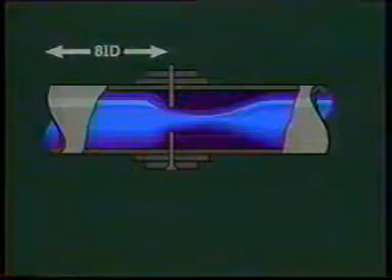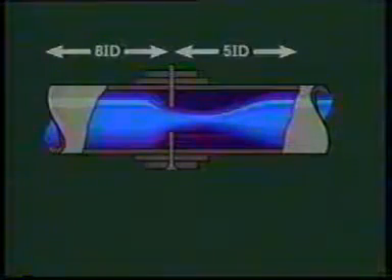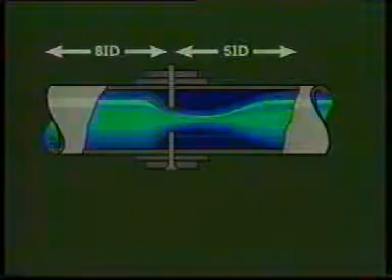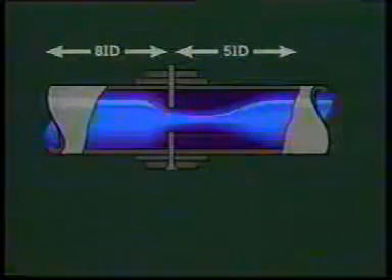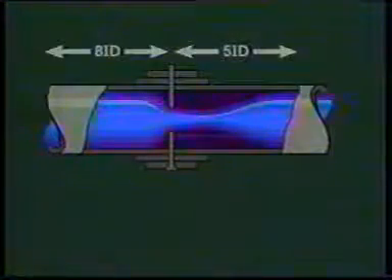The orifice flange should be installed in the line so that there is at least 8 pipe diameters of straight run on the upstream side of the orifice and 5 pipe diameters downstream. This will reduce any turbulence in the pipe that could affect flow measurement. You'll often hear this arrangement called an orifice run.